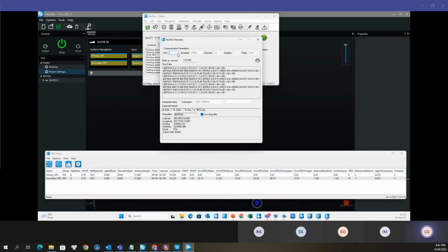But if I then choose COM4, then I'm using the information. You see, string filter doesn't have an effect here, and that's basically because we've changed the string filter to $GPG. We're not filtering anything away, as a matter of fact. Station and satellite information is available, and that's the information used to populate the last columns to the right here.